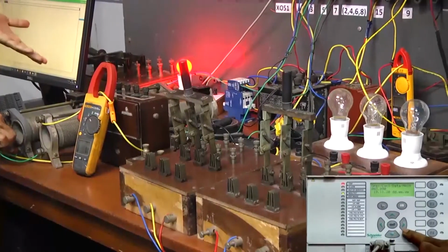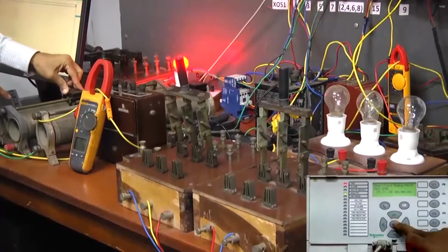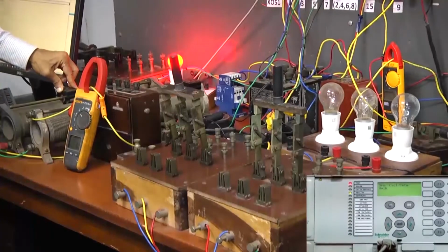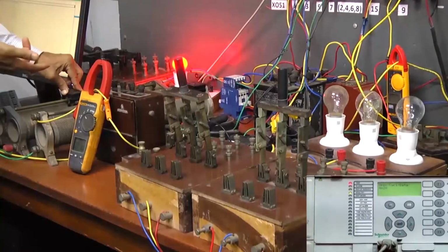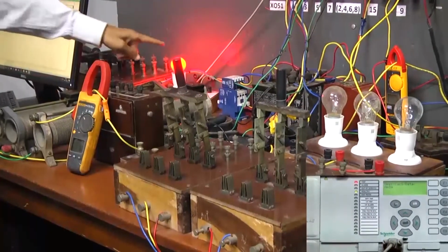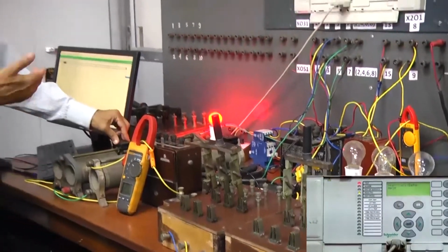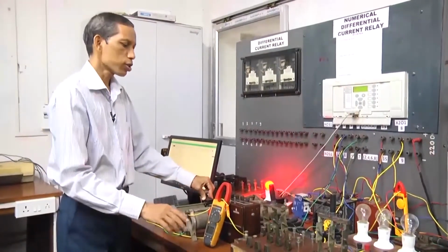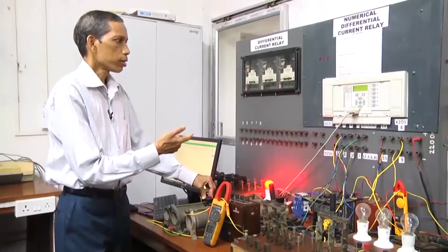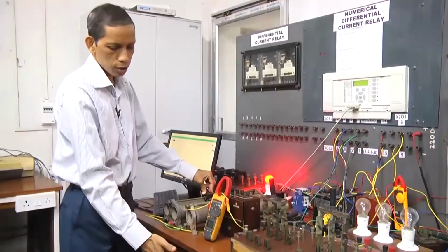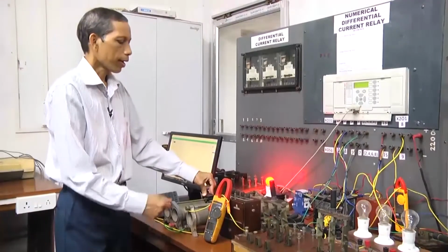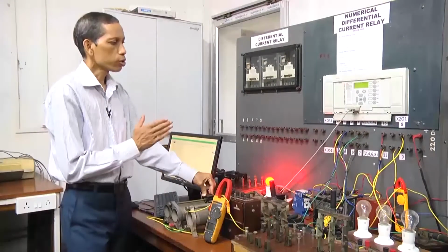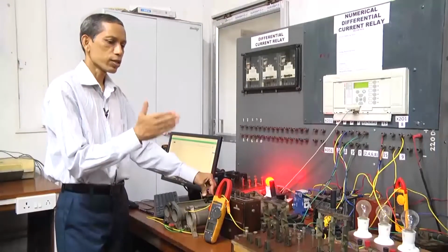So, that gives us that yes, at a particular point of the differential relay characteristics, the corresponding relay takes the decision and trips the particular breaker here. And like this we will go on noticing at different loading conditions, increasing the loading condition using the corresponding loads, and for that we go on varying the differential current, which will be more and more as per the characteristic curves.